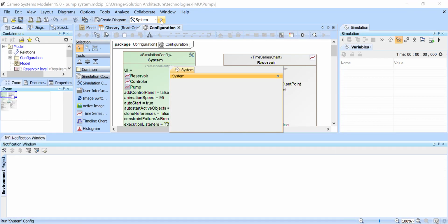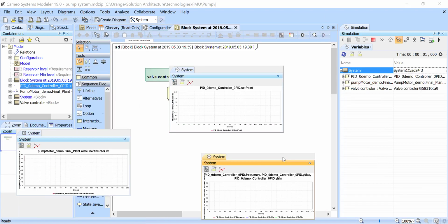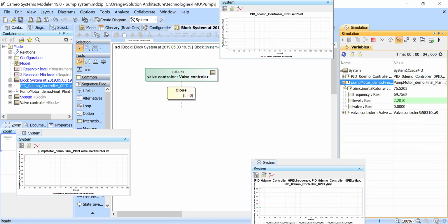So now we'll see only state changes, and it shows at what time the state was changed, right? So the valve controller at time 0 is closed, the initial state, right? Let's continue execution. And you remember it reached, it's open, right? So at 17 seconds, and then we will see that in 20 seconds it will switch to closed if we wait for that time.